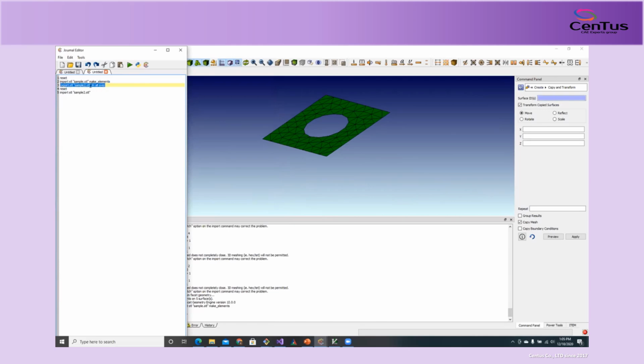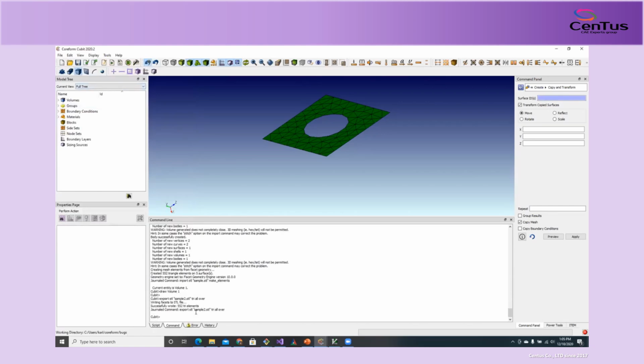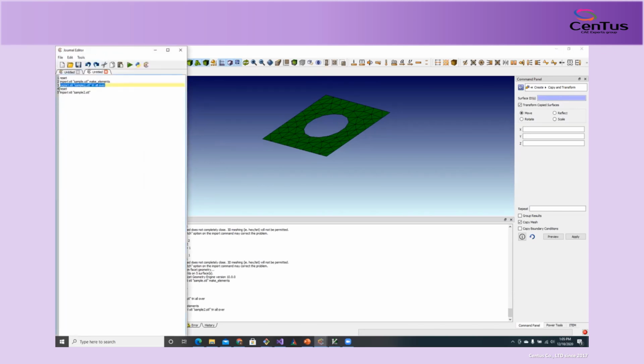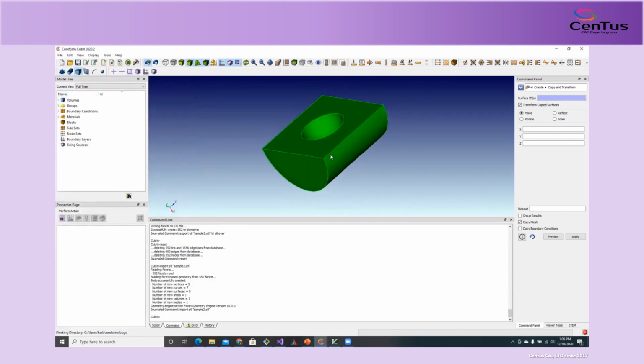And I'm going to say, export this all, triangle all. I just want to put all the triangles out, and I want to export it as a single volume. So I'm going to go ahead and play that line. Export STL sample 2.stl try all. I'm giving it the overwrite flag because I've run this several times already. I'm going to reset and read this back in. And now all those volumes are colored as one volume instead of having these things come out.